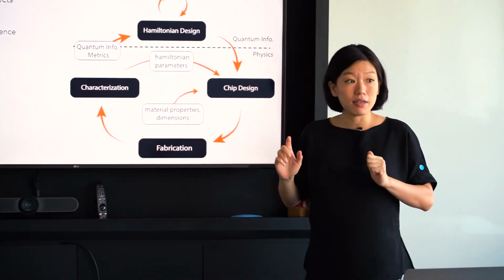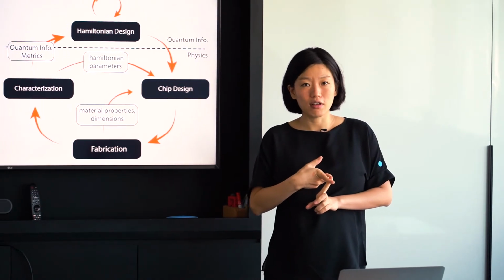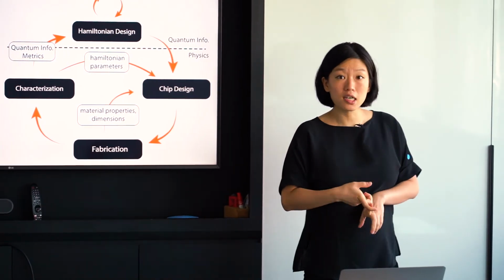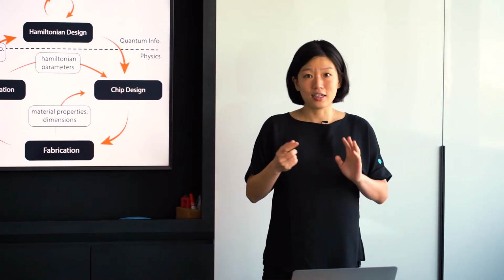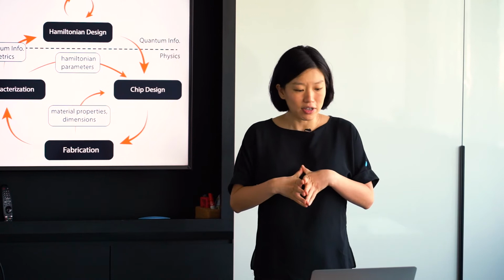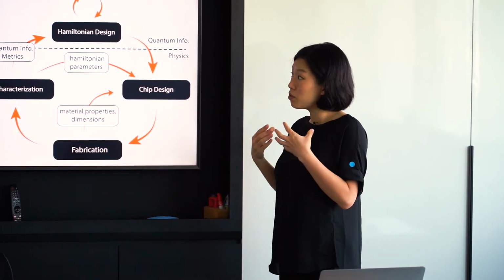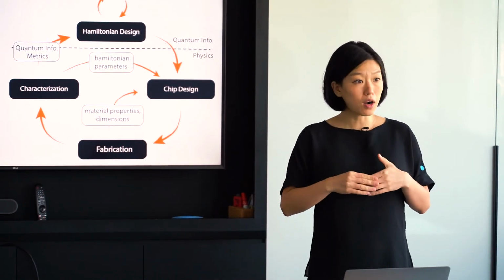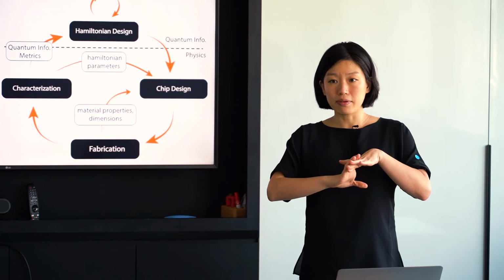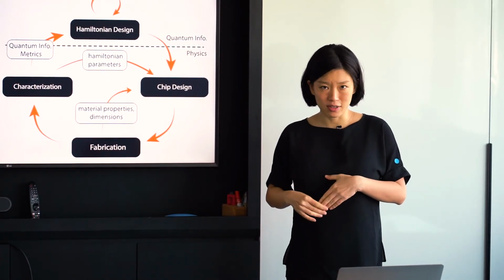And that's because maybe some of the devices didn't physically achieve the parameters that they wanted, or the performance was not up to par, or there are things like collisions of their frequencies that render them not very useful. And sometimes physically, we could also face the problem of some parts of the fabrication not working, right? When you needed an overlap, it's just not there due to some small imperfections in the process.